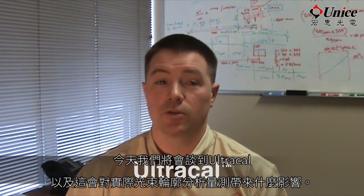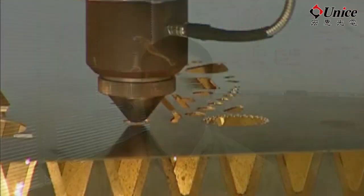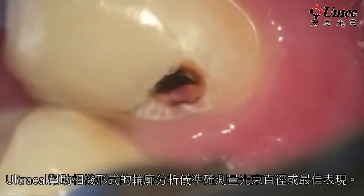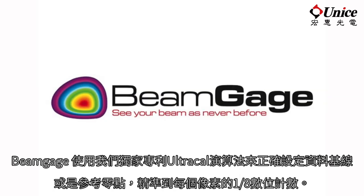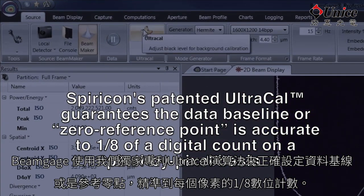Today we're going to be talking about Ultracal and what a difference it can make in actual beam profiling measurements. The performance of today's laser systems can be strongly affected by changes in beam diameter. Ultracal helps camera-based profilers accurately measure beam diameter for optimal performance. BeamGage uses our patented Ultracal algorithm to properly set the data baseline or zero reference point to as accurate as 1/8 of a digital count on a pixel-by-pixel basis.